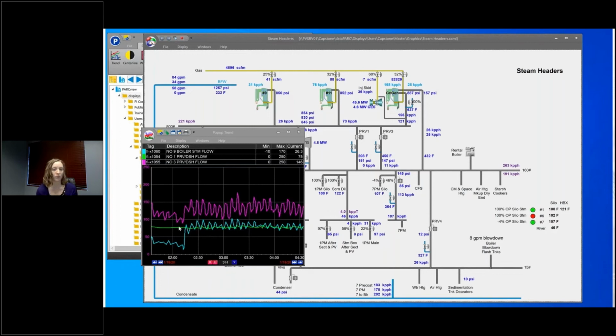So PRV1 looks totally flat. We'll go ahead and get rid of that one and just look at this PRV2. That has some oscillations that are worth considering. And then the question is, is it the PRV oscillating because users down below are, or because of the control system itself? So we looked at all of these different users down here, and they were all flat besides a few. So we'll go ahead and grab those key tags that we noticed were potentially oscillating as well.